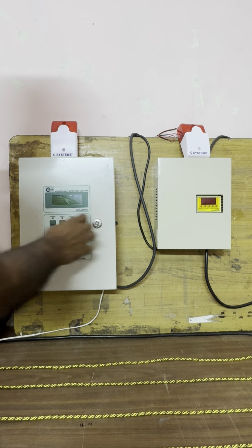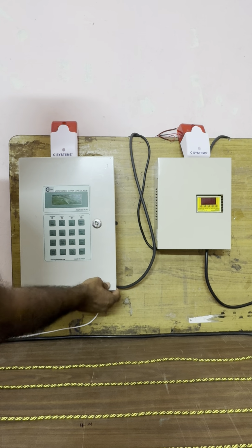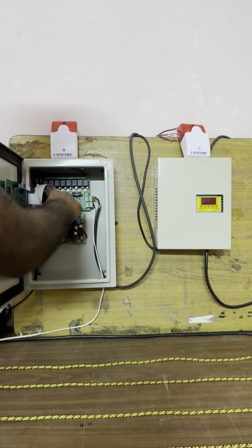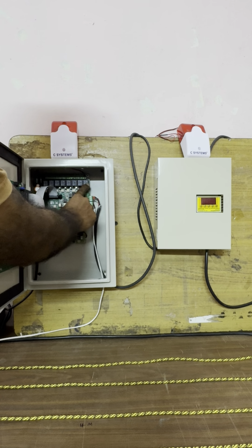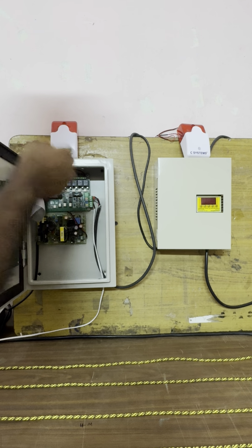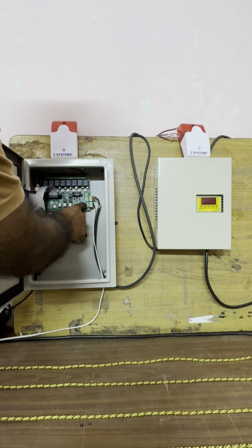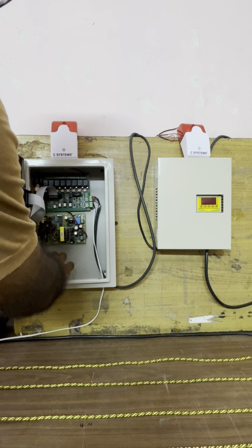In the master panel there is an LCD and a keypad for displaying the parameters and programming. We have 4 programmable relay outputs, 1 fire output, 1 fault output and 1 hooter output. These are the outputs that you can connect to third party systems for integration. Apart from the hardware integration, we have a soft point integration which connects to the BMS or through our proprietary software, which can show the leak detection and location in a graphical format, which I will explain a little later.